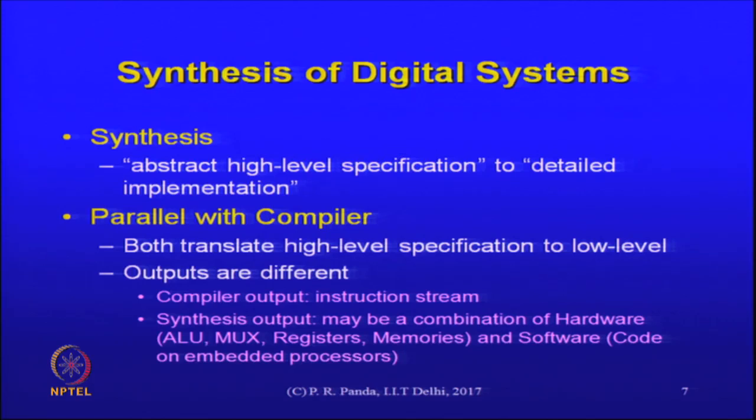A simple definition would be: synthesis is the process of moving from an abstract high level specification to a detailed implementation. The context here is that of an electronic design, but also within electronics we are restricting ourselves to a digital subsystem.